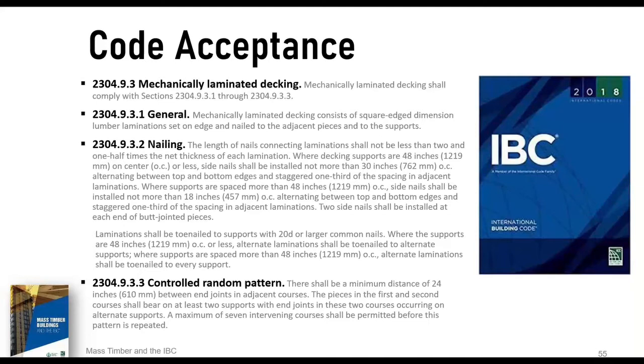Also, when being used as heavy timber floor or roof, Chapter 6 and 602.4.6.1, which refers to floors, and 602.4.7, which refers to roofs, call for the wood structural panel topping as it helps reduce the probability of a flame-through at any gaps that may exist due to the natural features in the individual wood members.